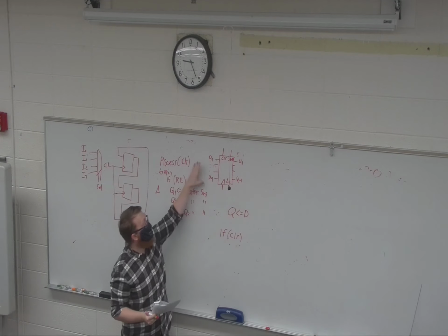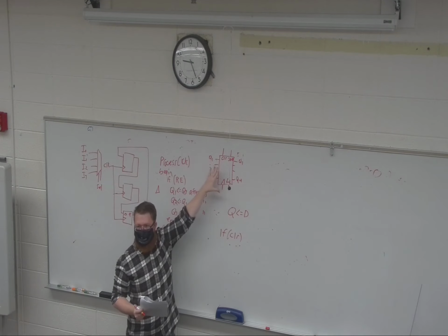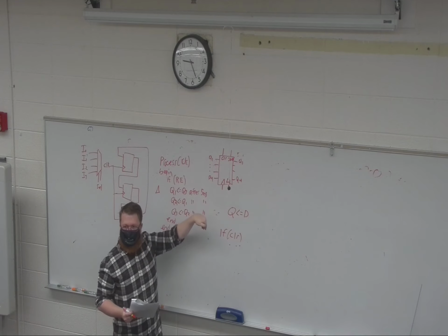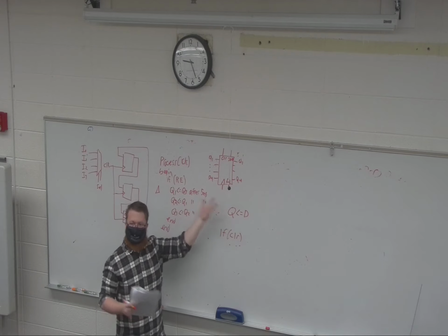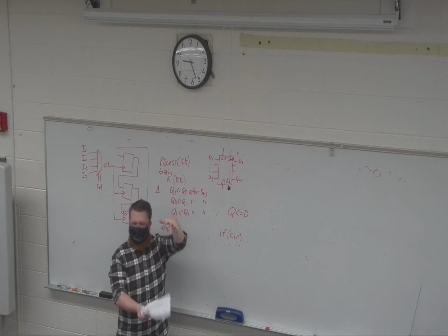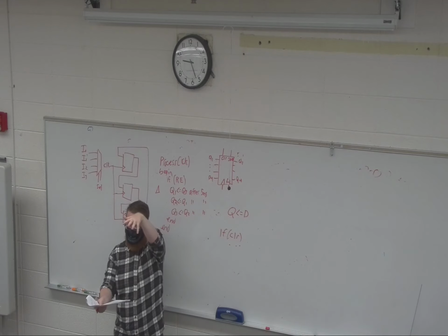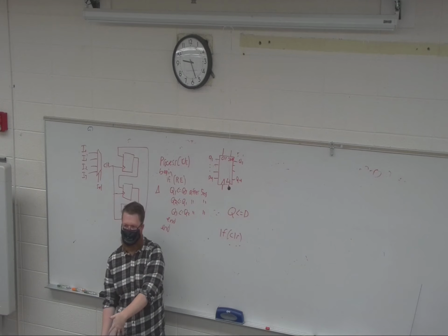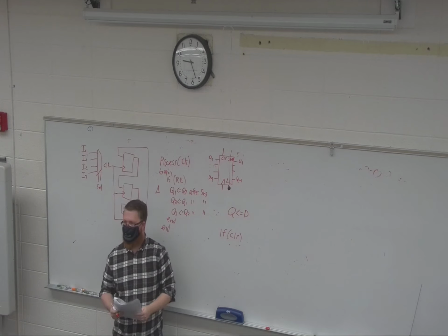And the 2 things that I could do is either load all of that data in parallel or shift it out one at a time. And that can be very useful in something like serial communication, where you have a big vector that you want to load in to be ready to be transmitted, and then transmit it out 1 bit at a time. That make sense, everyone?